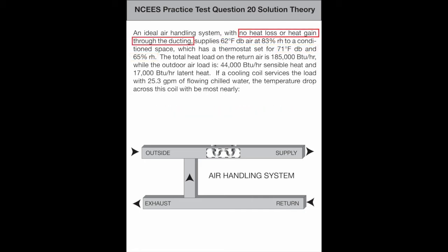Now, speaking of messes, the whole issue of heat losses or gains through the ducts due to fans or whatever indicates unnecessary information. Of course you have to ignore duct and fan contributions because there's absolutely no info in the question about ducts and fans anyway. You'd need data on the ducts, such as insulation, wall geometry, heat transfer, surface area, or on a fan, horsepower, efficiency, etc. There are ample indicators within the question that you are being given a mess. These messes are testing you on understanding a critical issue in HVAC.